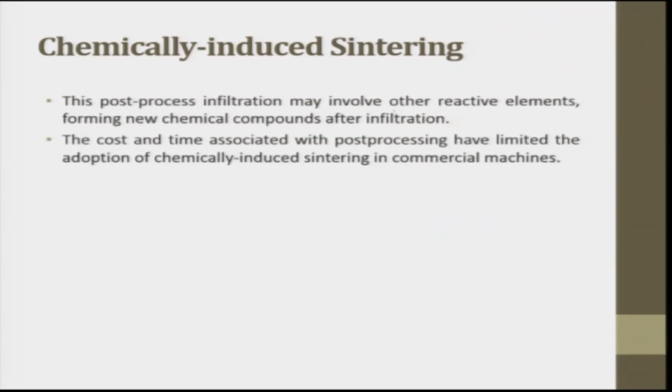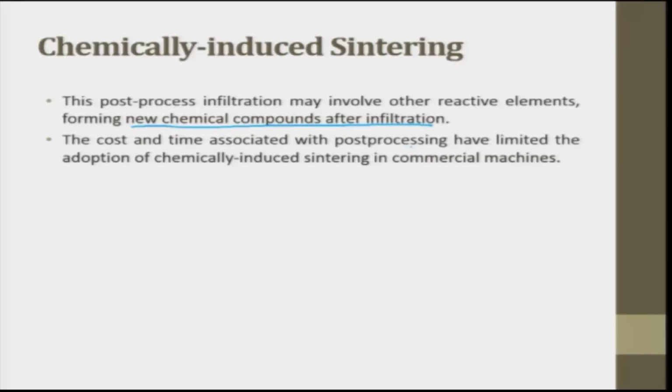This post processing infiltration may involve other reactive elements forming a new chemical compound after the infiltration. What I was talking about is, with very high pressure, the infiltration is pushing the liquid inside the pores. At some point of time, this liquid also can react with the base material and form one more compound or another reactive product which can be used for our benefit. The cost and time associated with the post processing have limited the adoption of chemical induced sintering in common machines.